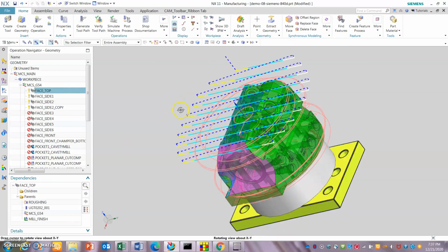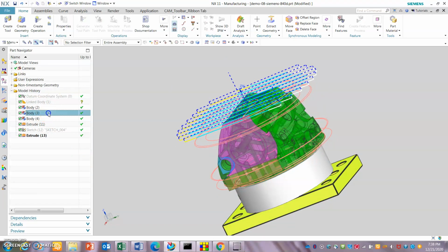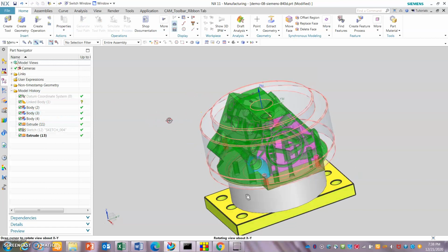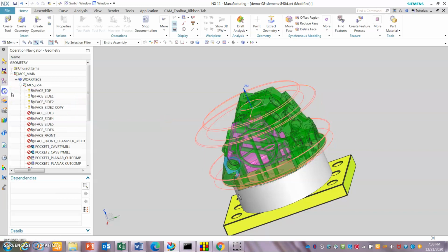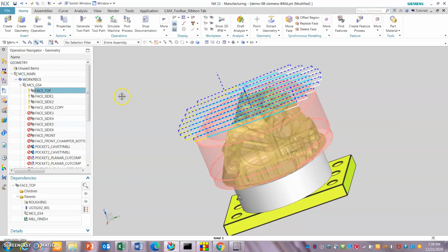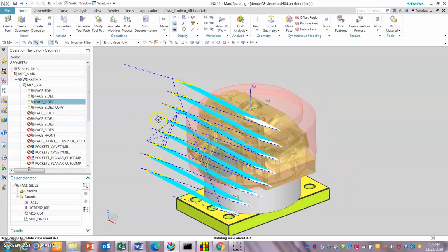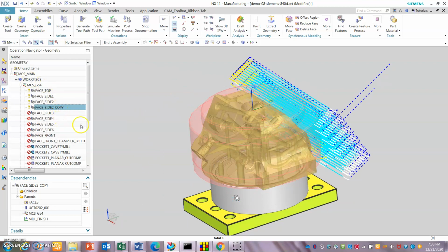So this is the blank, the highlight I'm showing. Okay, it's a round stock. It's held from the bottom through cap screws, like 6 cap screws, and located with diamond pins. The top face, the side face. Okay, this side, this side. So now we have examples of all the different angles.